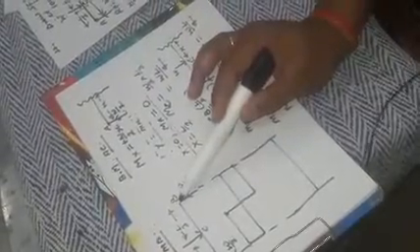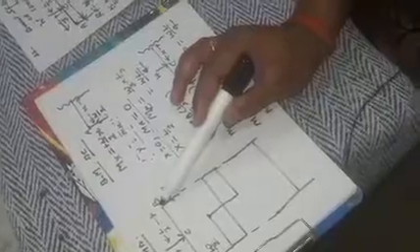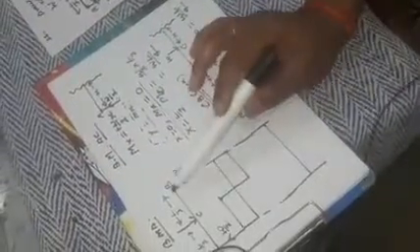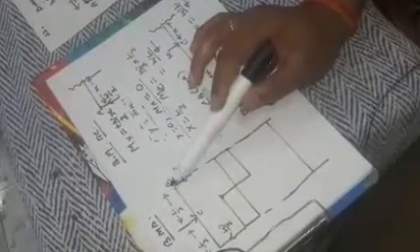And for point B, when we calculate, we will see that the value is 0, because when we move from right to left, from B to A, x equal to 0 will be here, so for point B, MB equal to 0.